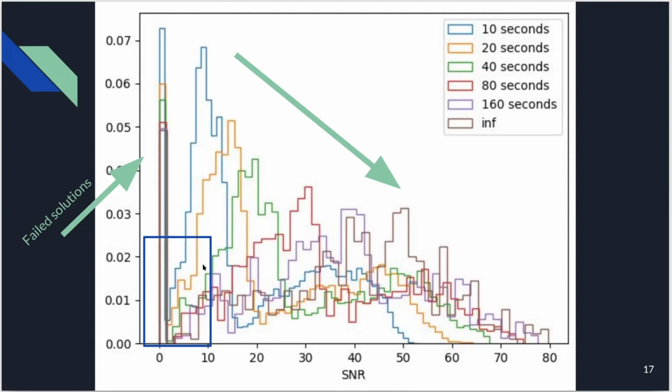And then you can also look at, this is an area of interest if you're using this way to choose an optimal solution interval. It is the area in which it's close to where the solutions will be flagged, in that the default is a signal to noise ratio of 3. So you can see as you go to higher solution intervals, you get fewer of these solutions that will end up being flagged.